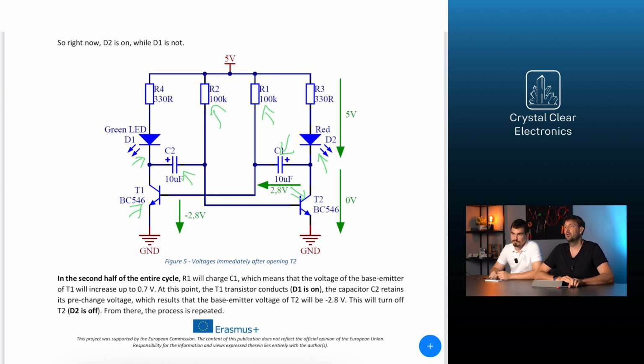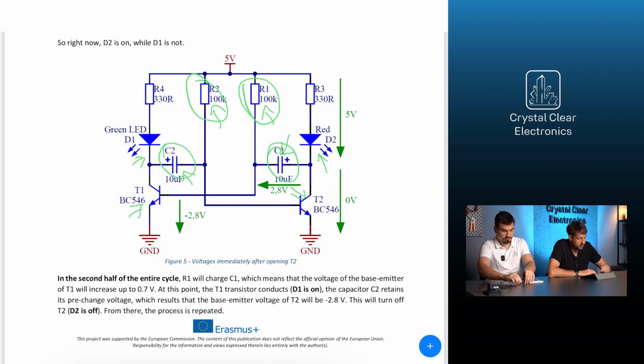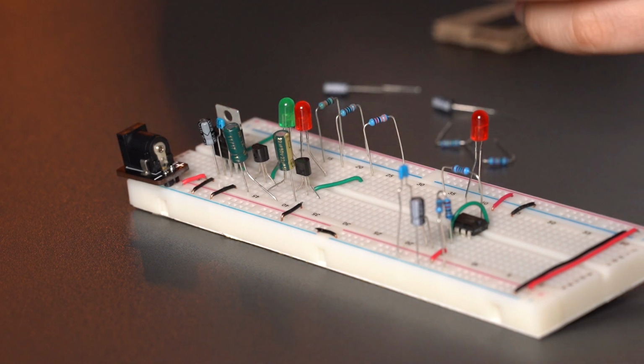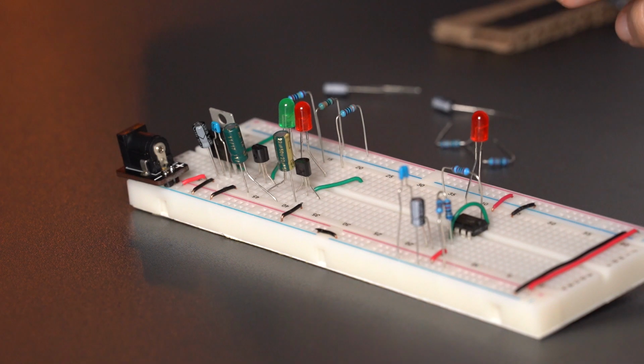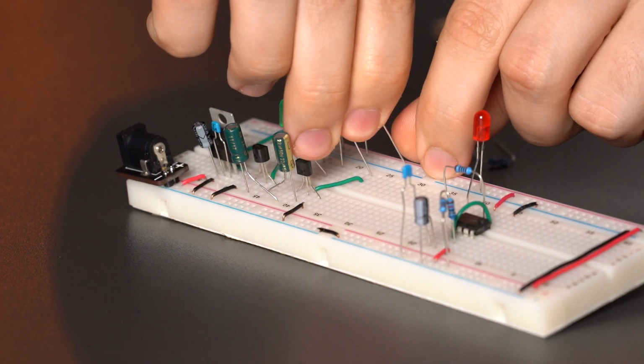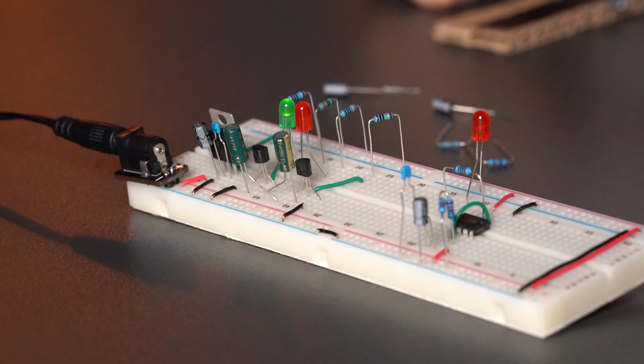The principle of operation can also be checked by measurement. Replace R1 and R2 with 1 megaohm resistors, C1 and C2 with 22 microfarad capacitors, and then turn on the voltage on the circuit. The replacement of the components was necessary to keep the blinking speed much slower, so you can follow the change of voltage on your meter.